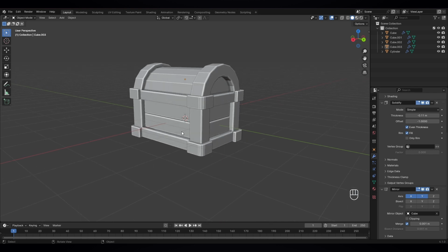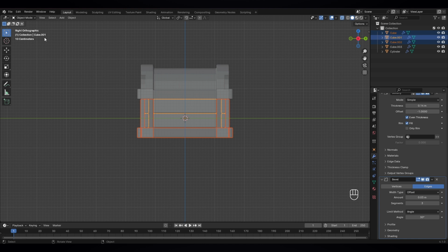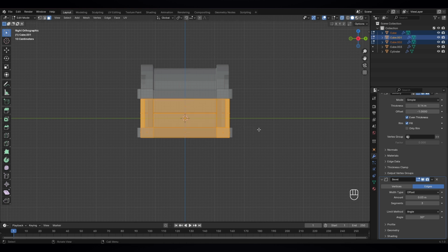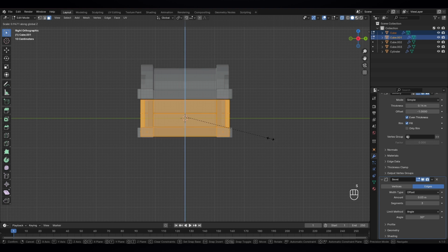and the next thing, I think this part looks a little bit bigger. Just select them all, go to edit mode, select them all, and S to, okay, not all, maybe just this part, and go to edit mode, S to scale on the Z-axis.